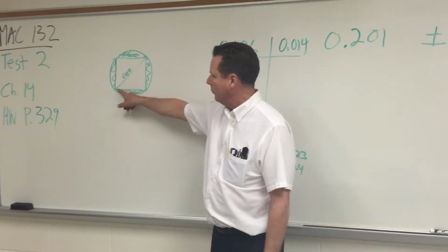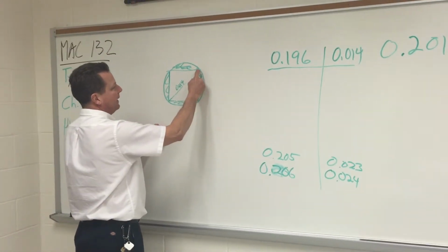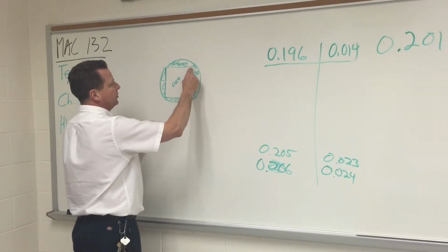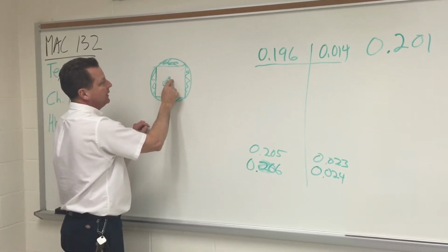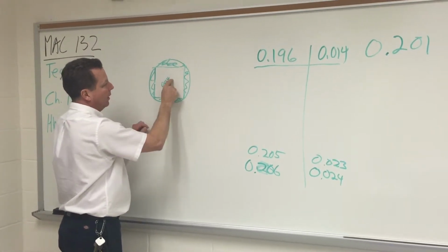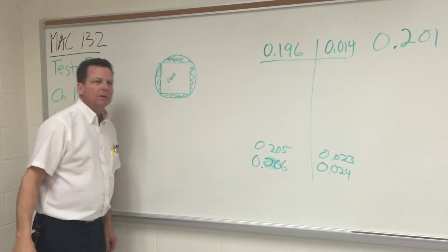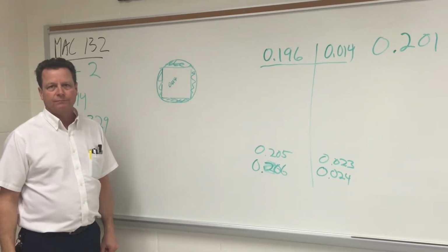So they found that when they did this, that if this were 10 thousandths and this were 10 thousandths, that was 14 thousandths across here. So if we had plus or minus 5, technically we could be 7 thousandths out off of the center here, and they would say that was a bad part, even though it would function.